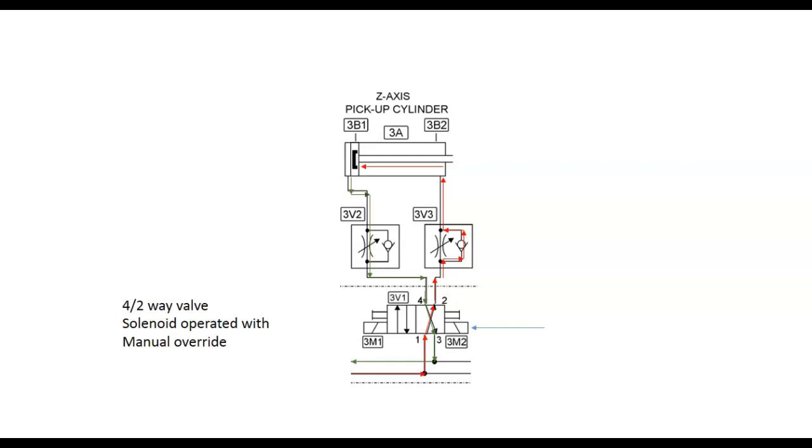Everybody okay on meter out? What does that mean? We control the air or the fluid coming out. So if you want, we can meter out hydraulics too. But in hydraulics you can meter in or meter out. In pneumatics we like to meter out when we can, especially on double acting cylinders, because you're always pushing against the pressure. If you meter in, then your cylinder's going to be what? It's going to be jerky, right? Everybody okay? That makes sense?